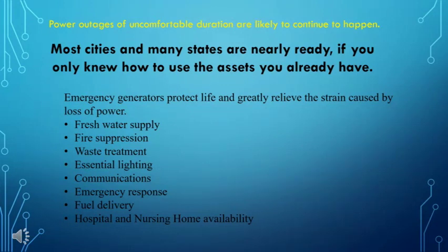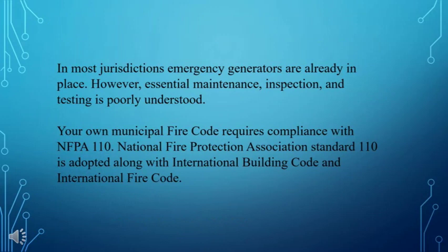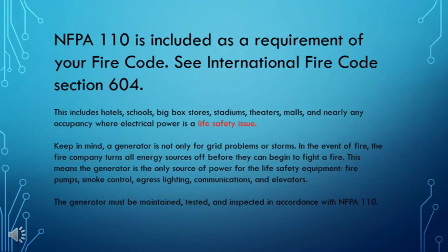are definitely considerations. In most jurisdictions, emergency generators are already in place. However, essential maintenance, inspection, and testing is poorly understood. Your own municipal fire code requires compliance with NFPA 110. National Fire Protection Association Standard 110 is adopted along with the International Building Code and International Fire Code. NFPA 110 is included as a requirement of your fire code. See International Fire Code Section 604.